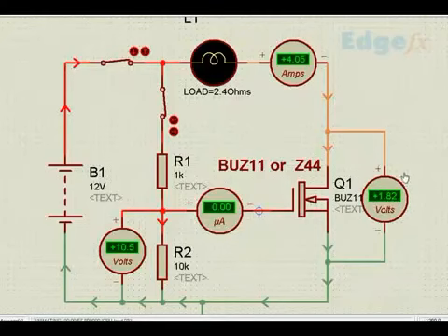Then this voltage can be fed to a comparator, which can in turn take any action, that is, switching off a device or even switching off the gate current here itself, so that this itself switches off. So that is the biggest advantage of understanding the RDS of the MOSFET, so that it can be used for a specific purpose.